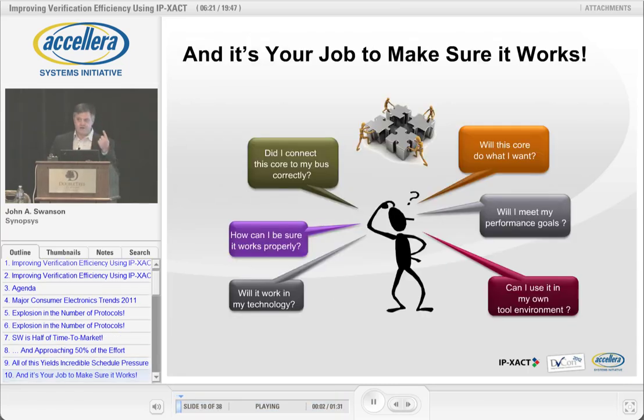And you're here at DVCon because it's your job to verify this stuff. And there's a lot of different things you need to think about. They're all little pieces. Did you hook it up to your bus properly? I see cores hooked up to on-chip buses, whether AMBA or your own internal OCP, incorrectly all the time. And people don't catch it in their verification.